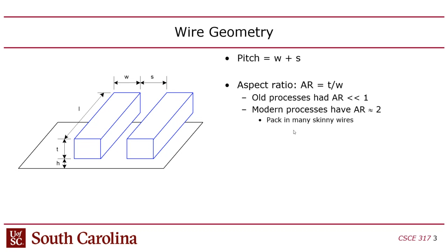It's hard to know what any of those things are until you actually design your chip. Generally, once you design the chip, you use a process called extraction, which extracts the capacitance and the resistance from the layout of the chip, from the design of the chip. Then you can simulate the extracted designs in a circuit simulator, which would include the transistor models, the transistor behaviors, as well as the parasitics, which are the unintended capacitances from the design of the chip.